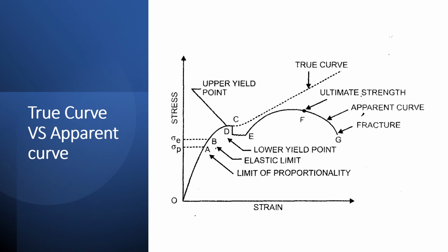So these are the stages of the stress strain curve. The first one is proportionality limit. Second point is elastic limit. Third point is yield limit. Fourth one is the maximum peak point before breaking, that point is called ultimate, and the last one is breaking.